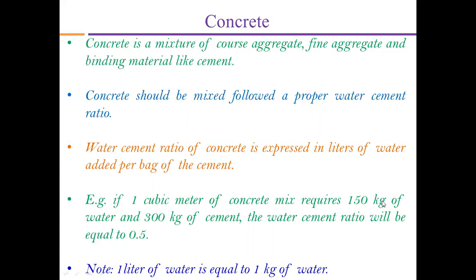Okay, so now the question arises, what is 150 kg of water? Just as a rule of thumb, you must keep in your mind that 1 liter of water is equal to 1 kilogram of water. Okay, so that doesn't mean that you will have to add water in kg in the concrete in the field. No, the answer is no. You will have to just add water in the field in the concrete in the form of liters.